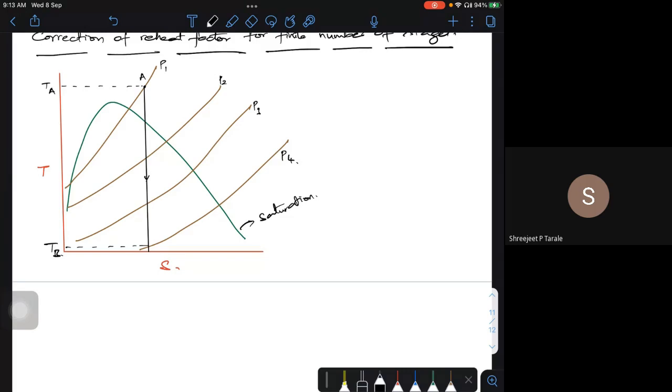So with a higher number, maybe the efficiency will be different, and if you go back and look at it, the curve will become steeper and steeper. With a lower value of reheat factor, it becomes flatter and flatter. It's not a very low value, but that's how the condition will look. Now, if I go for an expansion and it follows a simple straight line, okay. If the condition is superheated, this is the curve I'm going to follow, the blue one.